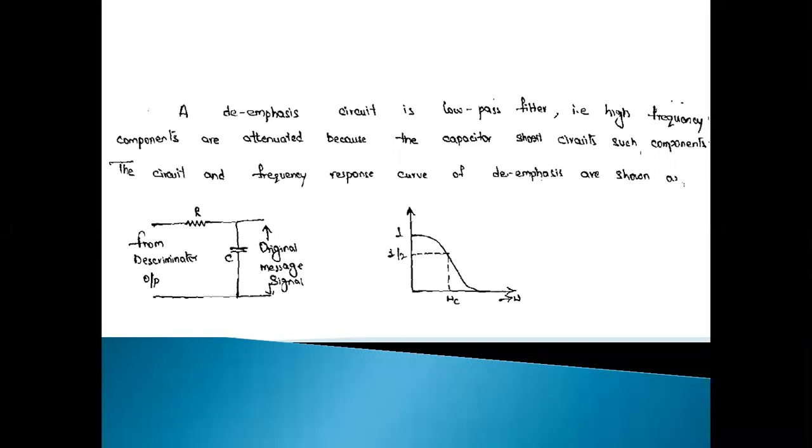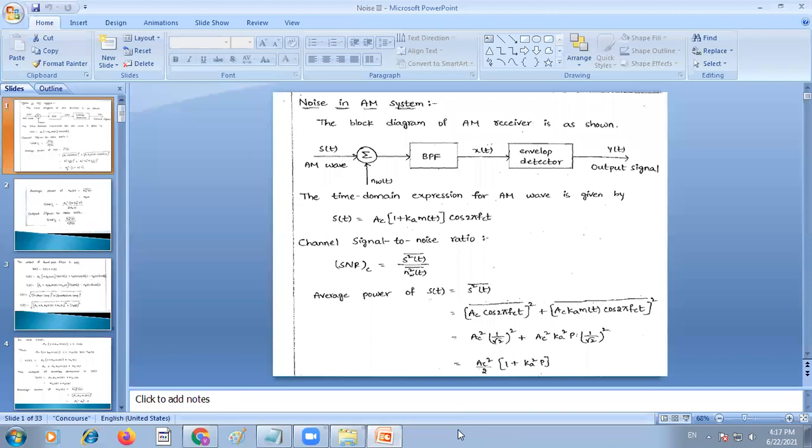That's why initially you have to select the de-emphasis network first, because you have to estimate the signal distortion. After the distortion is estimated, the pre-emphasis network is then initiated. So these are important topics in communication. In general, the distortion takes place at high frequency components. In order to eliminate the distortion, you can go for pre-emphasis and de-emphasis.